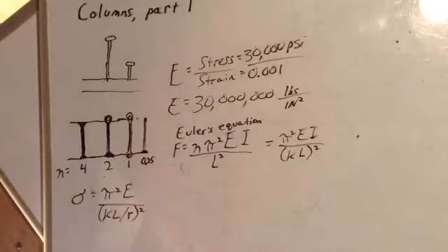If you watched our gyroscopic precession video, you're familiar with the term radius of gyration. It was defined as, this would be the mass radius of gyration. It was defined as the radial distance from a given axis at which the mass of a body could be concentrated without altering the rotational inertia of the body about that axis.